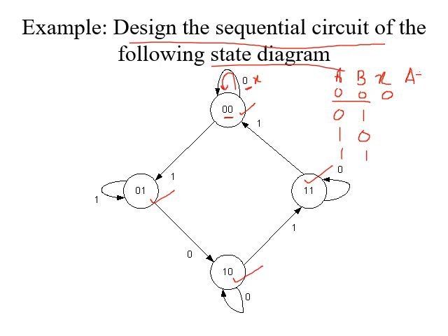A plus means the next state which will be coming, and B plus is denoting the other bit for that next state, because the state is represented by 2 bits in this case. So when we were in the state 0 0 and we got an input x as 0, the state remained the same. It came back to 0 0 itself. So we can fill A plus B plus as 0 0. This is the manner in which we can complete the table.